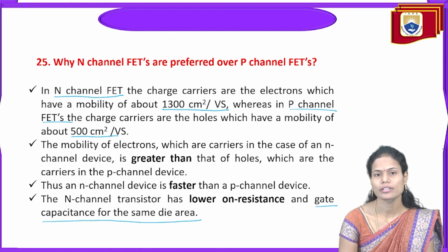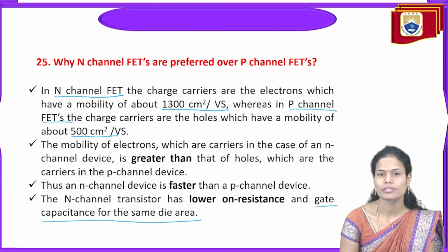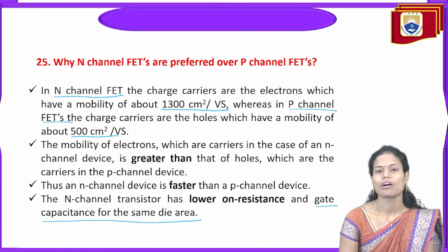The number of charge carriers is more, the movement of charge carriers is more, and those are faster, and the input impedance is less, and the capacitance of the device is very low. So that's why N-channel FETs are more preferable compared to the P-channel FETs.